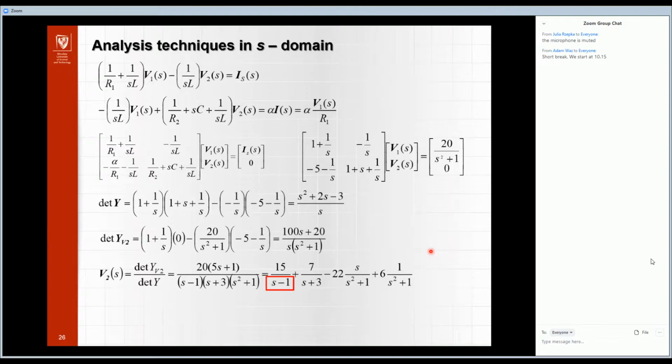But it is very strange when we obtain in the denominator s minus something. Because when we remember the pairs of transformation, we always have the plus connected with s plus something in the denominator, because when we transform such an element to the time domain, we obtain a decaying exponential, minus in the power of e.